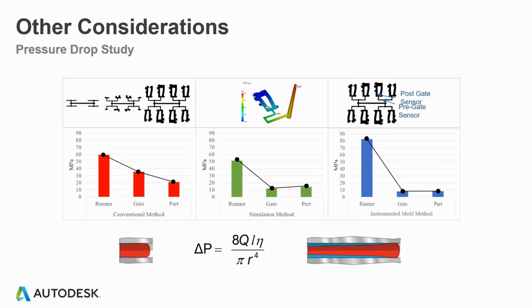So in this case, they may conclude that they could take a significant amount of pressure out of filling this mold if they were to, say, increase the runner diameter or open the gate. Many times we want to verify those results, so we kick that over to simulation. We say, hey, can you check out what I'm thinking here? Simulation comes back and says, okay, maybe the runner, but not the gate. There can be a lot of back and forth here.